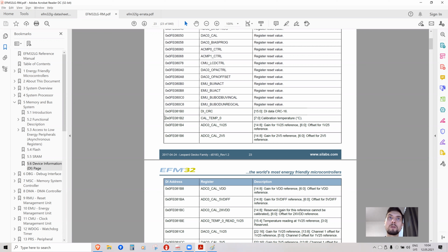However, yeah, now I get what the problem is. If we wrote it with a pointer, it wouldn't work, because this address ends with 2, but the memory is organized in 32 bits. So actually, we are not able to read from this address, most probably, because its flash memory is 32-bit wide. So we would actually read both numbers, and we need to extract this upper part from that address.